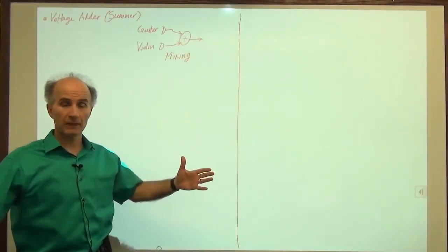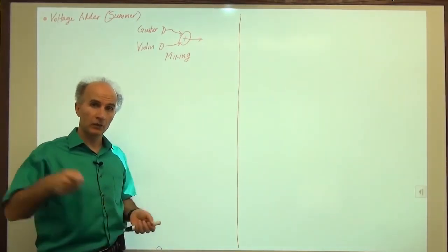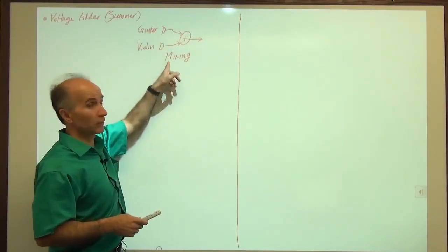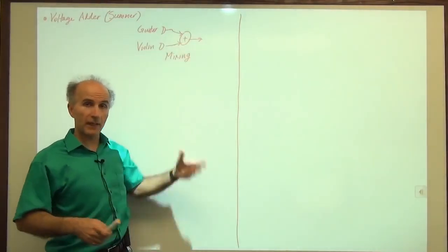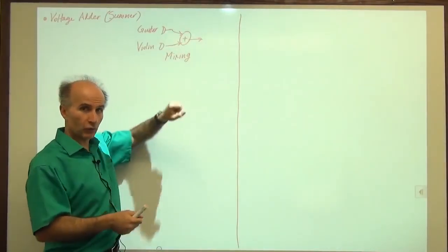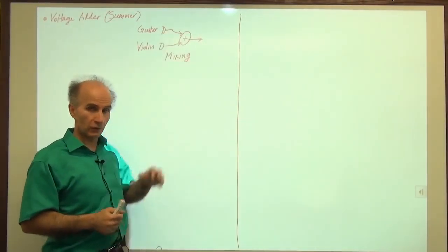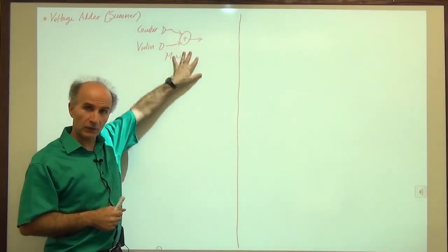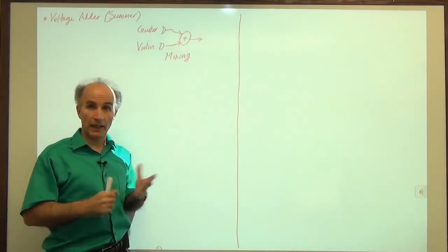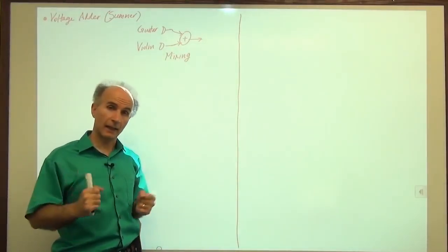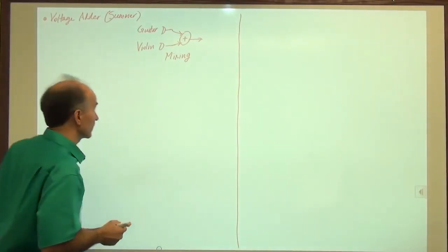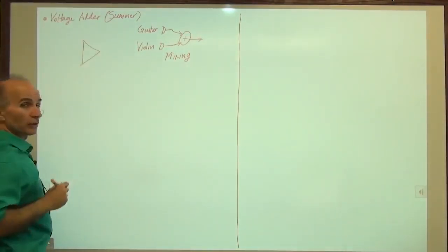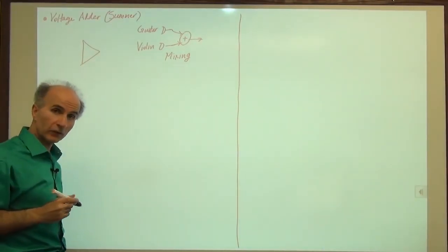So you have these mixing boxes that you can buy, and you plug in different microphones from different musical instruments, and then you can adjust how these can be mixed, what weighting factors should be used for these different instruments. All right, so how do we build a circuit that can do something like that? And an op-amp gives us a nice, elegant solution. So here it goes. We take an op-amp, similar to the inverting amplifier topology.